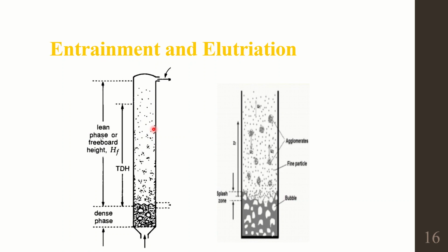In order to design the fluidized bed perfectly, it becomes necessary that we understand all these things. We cannot allow the particles to escape from the fluidized bed design. After this regime, there would be particles whose free fall velocity is very much less than the gas velocity, so their chances of escaping are high.